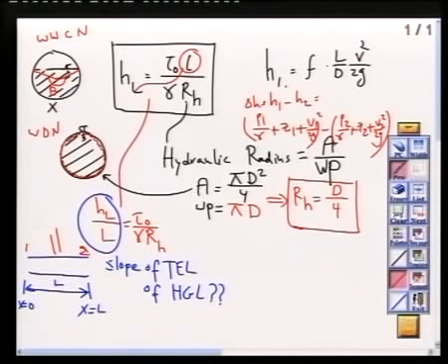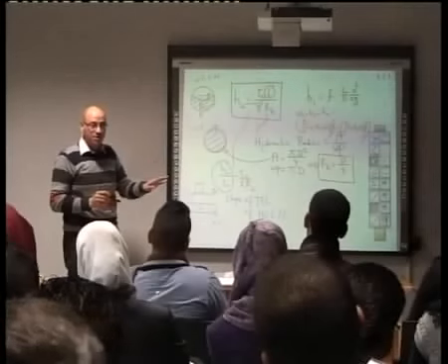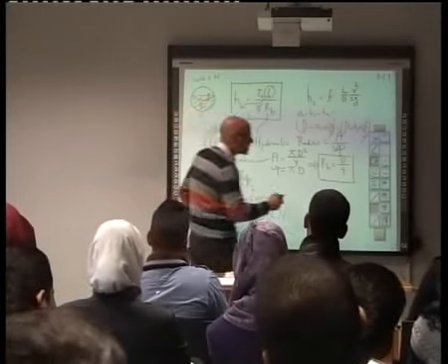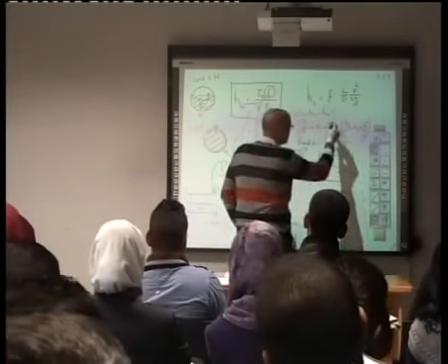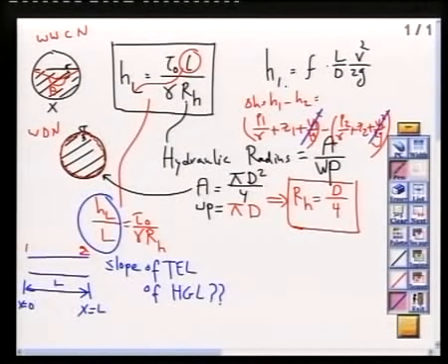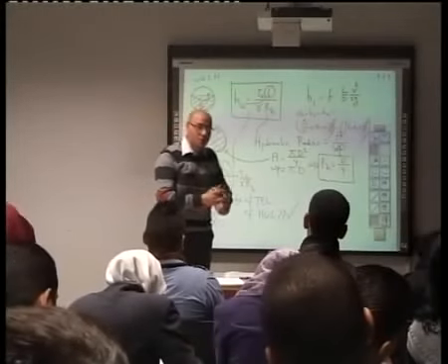So what kind of flow do we have here? Constant. Uniform. We have to use the word uniform. So in the case of uniform flow, V1 would equal V2. So it's correct, yeah. But we need to keep in mind that in general we are talking about total heads, including the velocity head.